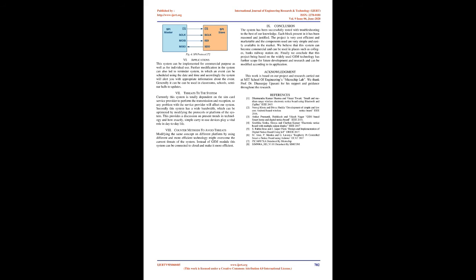It consists of 4 wires, but 3-wire communication is also possible. There are 4 SPI modes which describe the relationship between the phase of the clock line and the phase of the MISO/MOSI lines. In order to successfully communicate using SPI, the master and slave must operate using the same mode. Fig. 4, SPI protocol.